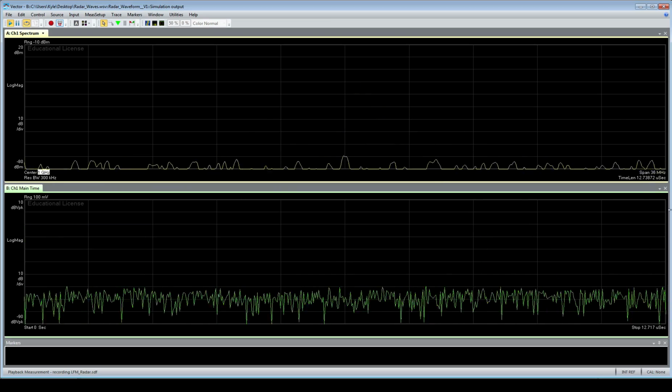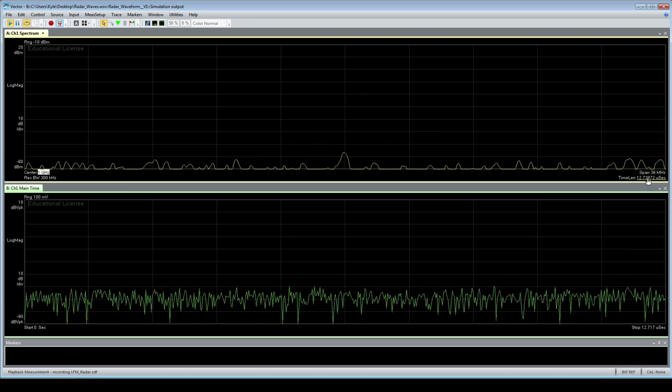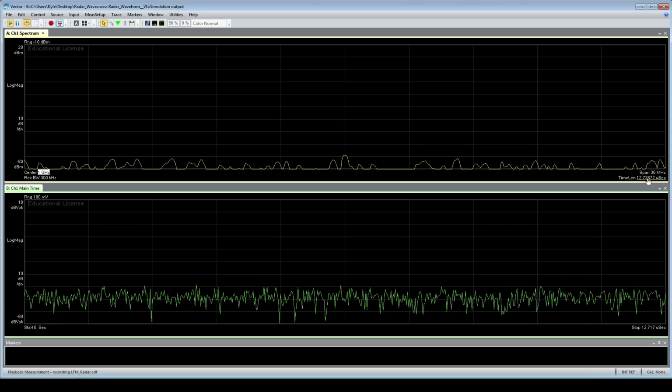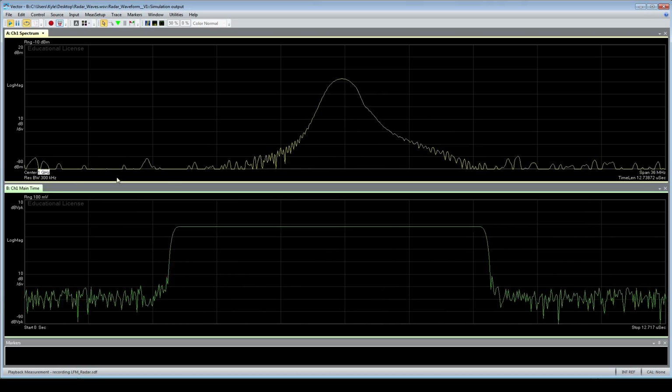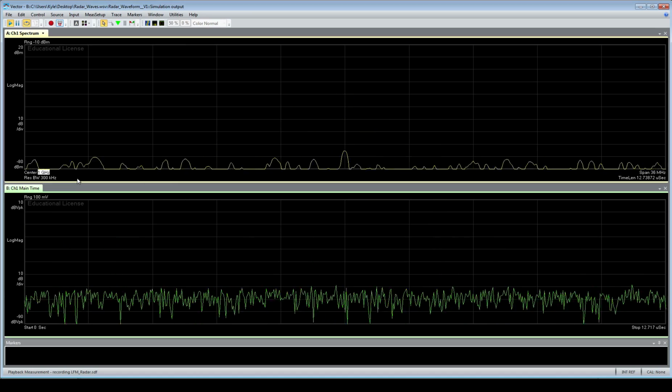And then it's got a length of time down here, and we can change the length of time we look at. Often it's shorter when we want to look at 1 pulse, and we want to see multiple pulses at the same time. We're going to increase the length there. And then the resolution bandwidth. And many of these things, as you'll see in a second, are tied together.